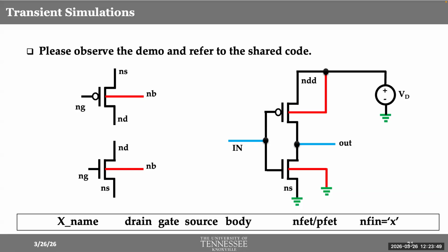Just so you remember, okay? All right, and then you have to connect the drain voltage as VDD, and source is grounded. PMOS body, remember, is connected to the VDD, and input and output are what we are looking at. And this is an inverter. What inverter does is inverts the input to the output, right? So we'll see how that works in a circuit setting together.